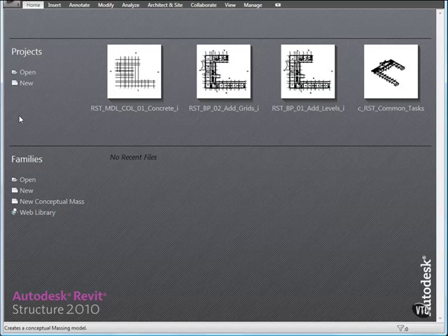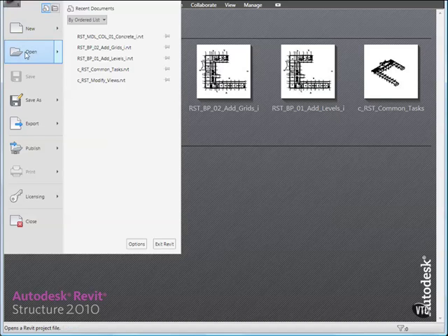In this lesson, you will add steel columns to the entryway of the structure at specific grid intersections. The columns will extend from the 01 entry level to level 02 floor. Click the menu browser and select Open Project.